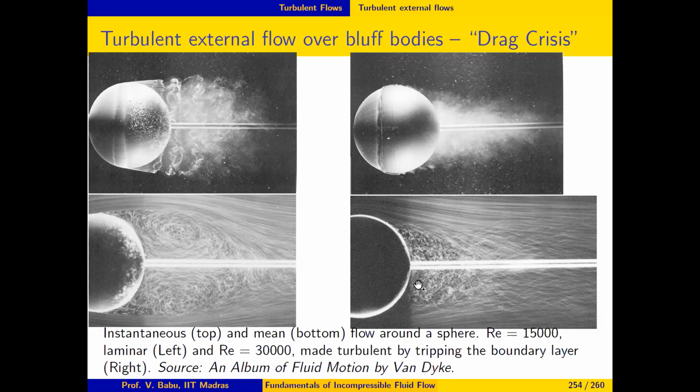So it is reasonable to expect in this case that, on account of the compact wake, the pressure drag would be much smaller. Skin friction drag probably is going to be higher on account of the fact that the flow is turbulent, but still the dramatic reduction in the wake size can be expected to give rise to an overall reduction in drag.